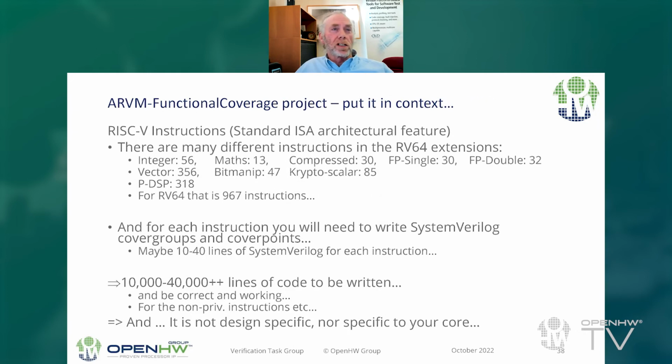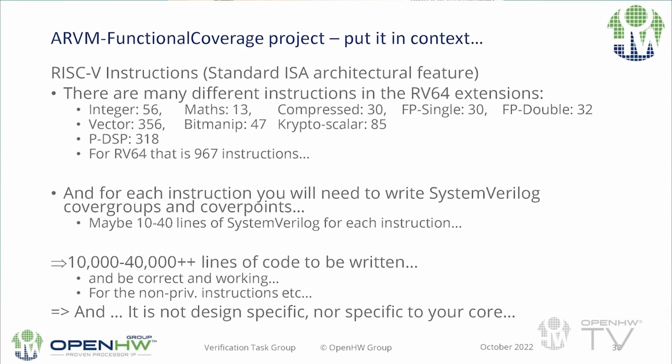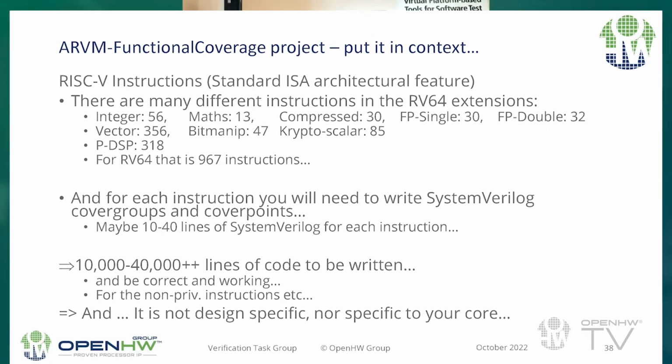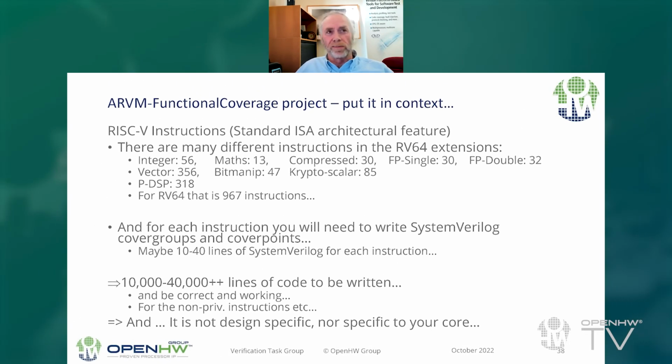If we just look at some of this to put it in context, RISC-V instructions: we counted this about six months ago, I think, and there are almost 1,000 instructions in the basic instruction sets that have been defined. That includes the DSP, which is currently undergoing revision, but there's an awful lot of instructions in there. And for every instruction, you're going to need to write some SystemVerilog.